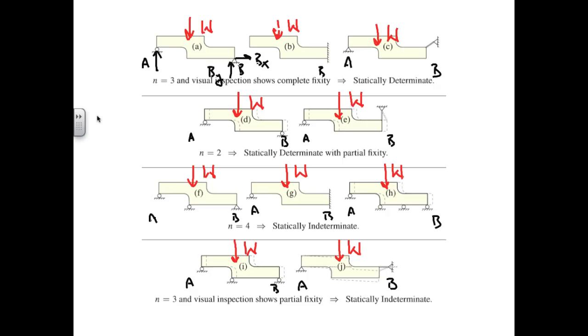If the roller were literally a roller, let's say a single ball bearing on which the left side of the structure were resting at A, then there would be no ability of the roller to pull down on the left side of the structure, and we could experience a rigid body rotation about the pin support at B without violating the support at A. But the roller icon is not meant to be literal. Unless stated otherwise, it is as capable of exerting a downward force as an upward force, and under these circumstances, no rigid body rotation is possible.